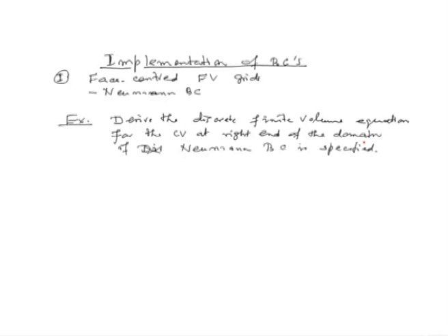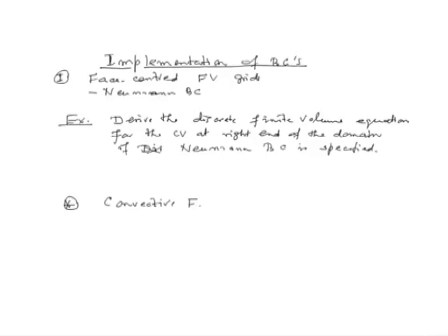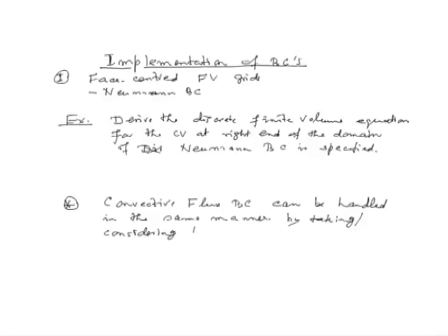Convective boundary condition in this case can be handled in a similar fashion. So, that I would leave with just a comment there: the convective flux boundary condition can be handled in the same manner by considering half width CVs linked to the boundary nodes.